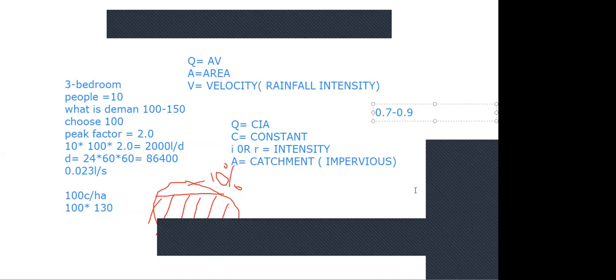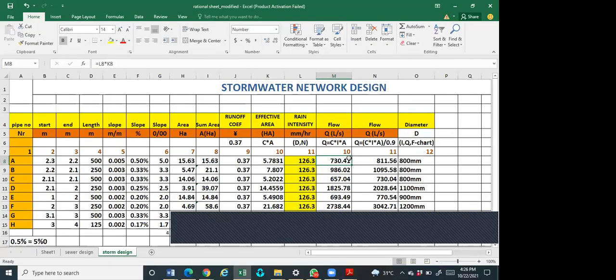So what I now did in this column was to say, I have gotten this value. Yes, this is okay. But I need to put a second level safety factor on it. So I divide this value by 10%. Some of us will agree with me that sometimes when you do your design, you multiply by 1.2. That 1.2 is just an additional safety, just to be sure that you didn't make a mistake. So when you do this now, it will give you this.